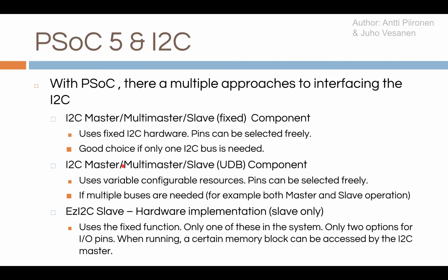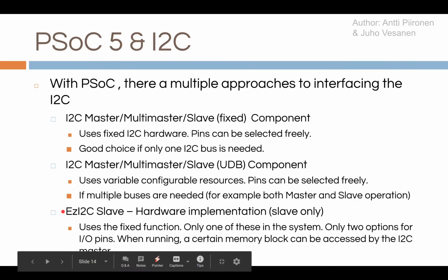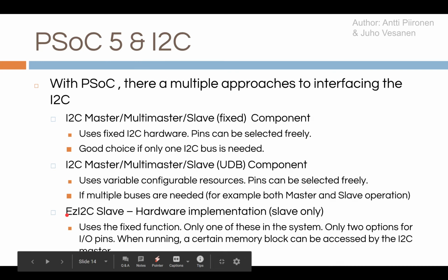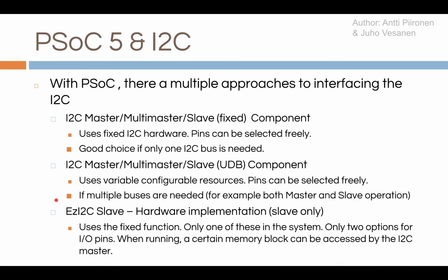But as I said, if only one I2C bus, then the fixed component leaves more resources for the other UDB components. Okay, then there's also slave mode, the easy I2C slave, which is a hardware implementation.